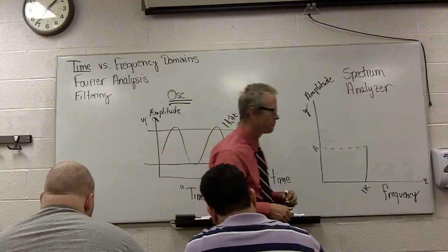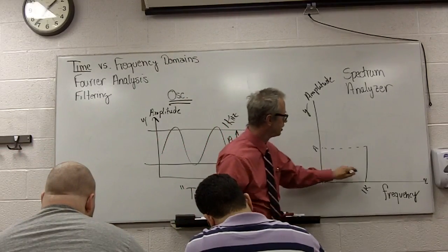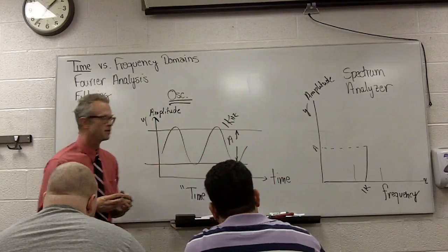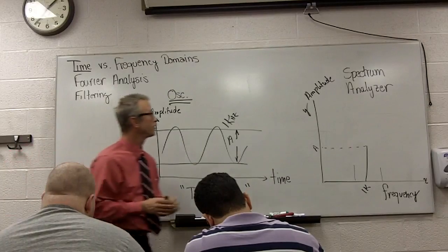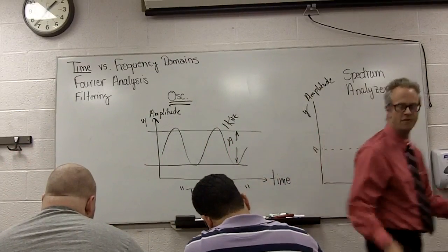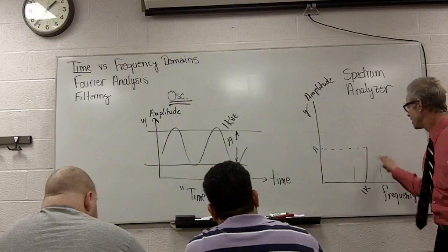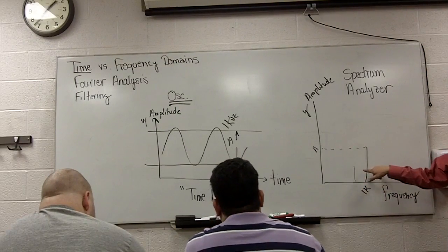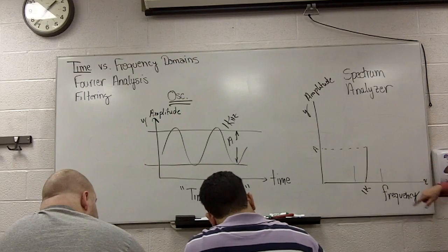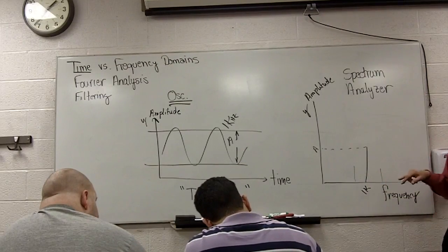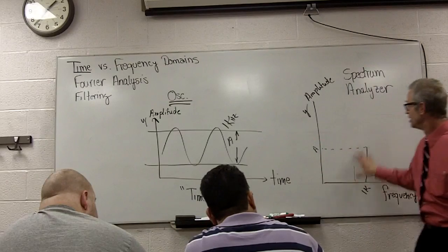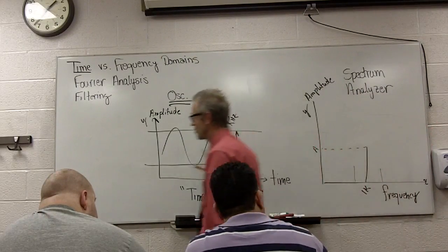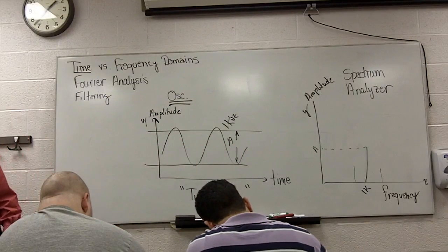Now, jumping ahead, which I'm not going to do much more of, but when you look at an AM radio station, it typically looks something like that. It has what we call sidebands. It has the carrier along with 2 sidebands. That's in your future, but this is going to become something that's very familiar to you. And the reason it's familiar is because we need to be able to look at it this way in order to tell exactly what's going on. In an oscilloscope, the waveform will not be as obvious. It'll be very difficult to calculate or determine what the frequencies are.